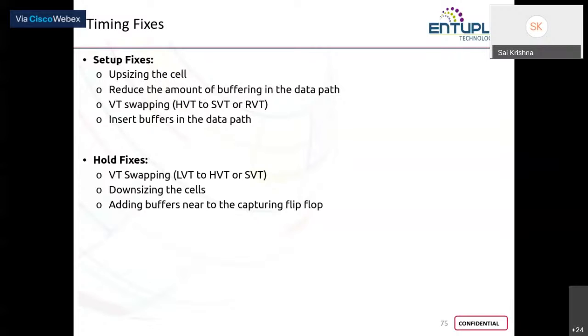So to keep it simple, if you try to improve your setup, it will degrade your hold. And if you try to benefit your hold, it will affect your setup. So it is like a two-edged sword, which you have to balance at both ends. Too much fixing of setup and too much fixing of hold is not recommended.